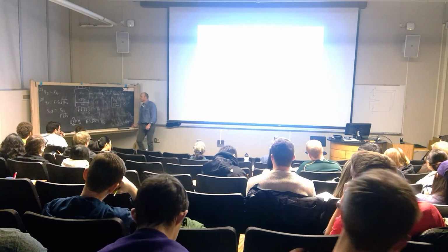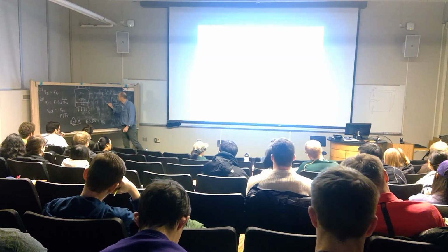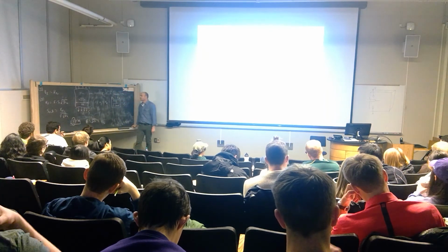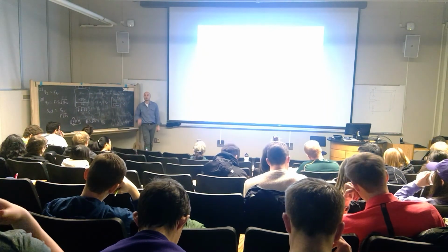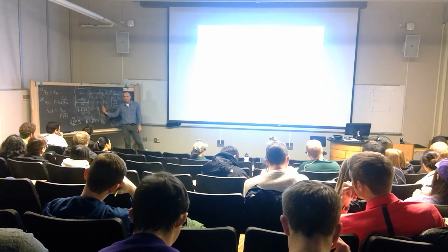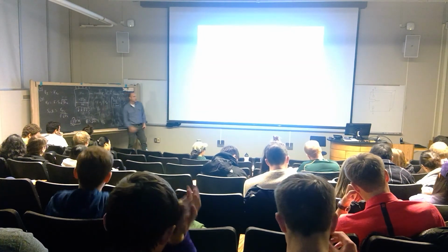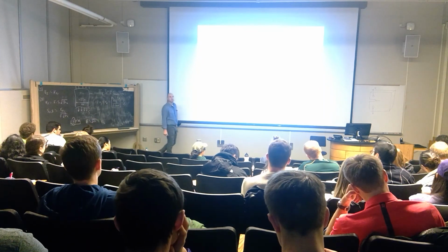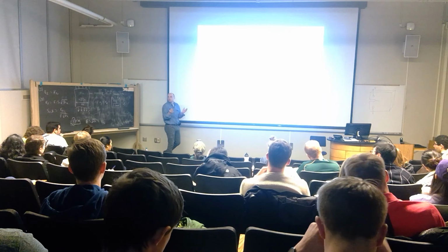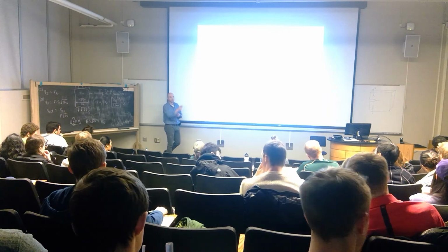I can estimate this a sub c, which is equal to my final crack length at fracture. So if I know my initial flaw length, and I know what my final, most likely flaw length will be at fracture, I can estimate an apparent life. And then with that, I can decide, hey, I only want to use 2/3 of that, and take that structure out of service before that.